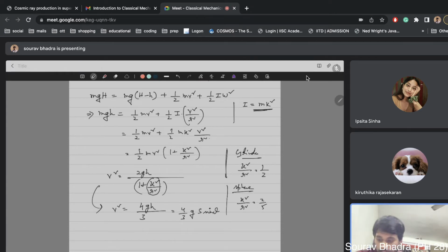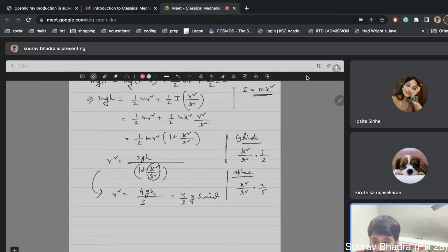So this is now your equation, and it is like a differential equation, 4/3 g s sin theta. Your theta is constant, and if you write v as ds by dt, that is v equals the square root of 4 by 3 g sin theta times s, and by integrating both sides you can get the result, what will be the distance s after time t.